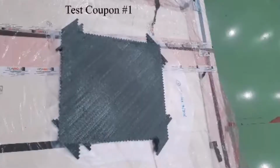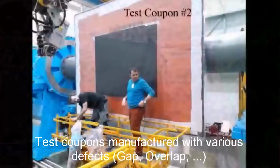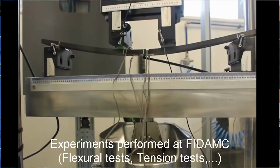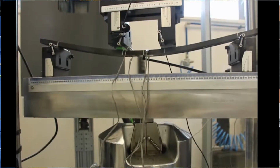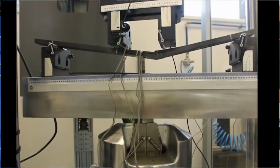The second approach allows a more detailed analysis. Here we generate a full 3D solid element model of the zone around the defect. In fact, two models are created, one with the defect, one without. Loads from the global model of the whole structure are retrieved for the defect zone and applied as initial boundary conditions. Finer element analysis is carried out on these models, and comparison of the two models allows a measure of the change in safety margin.